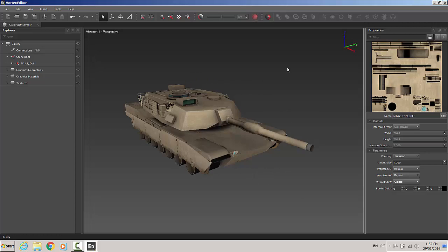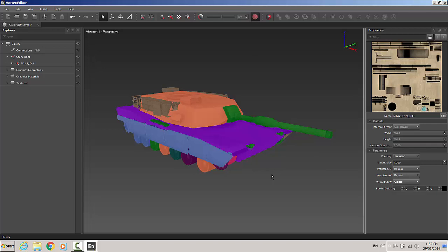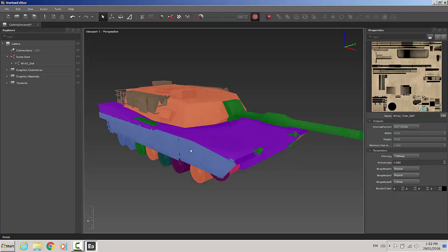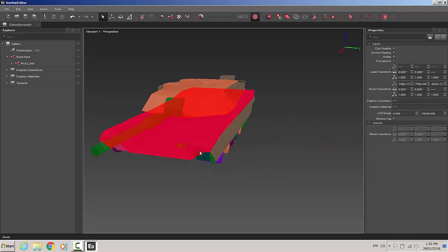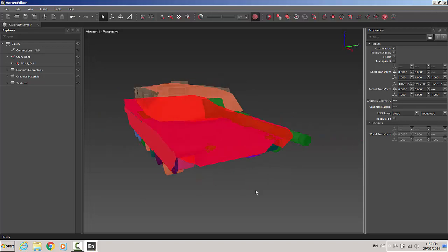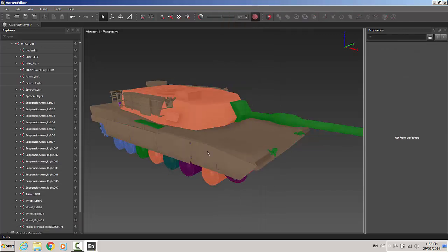There are a number of tools accessible. In this case, we'll still use the Colorize Node tool to show us what the model is made of. There is a separate node for the side panel and the hull, but we don't really need the side panels to be a separate part. So we're going to merge them with the main body to have a single node to cover everything.